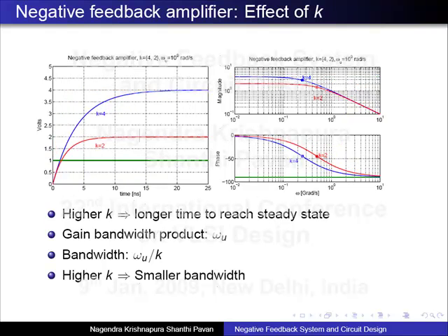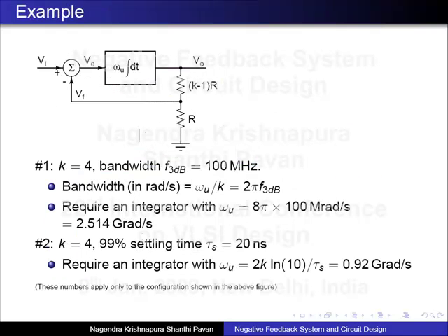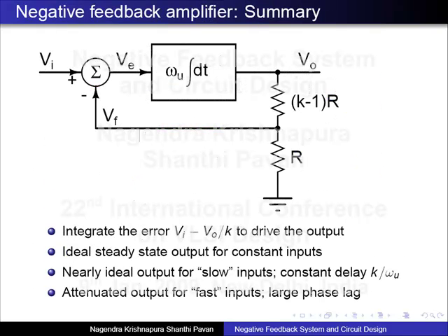No, I think, see, what I'm calling an integrator is this block. What I'm plotting is the response between here and here. Between VE and VO, it is perfectly an integrator. Between VA and VO, it's not an integrator. It's not supposed to be. It's supposed to be an amplifier. Now, because of the limitations of the integrator, it doesn't behave like an amplifier in some region. So I never said that between VA and VO, it's an integrator. Between VE and VO, it is an integrator. And as far as we are concerned now, it is still a perfect integrator.